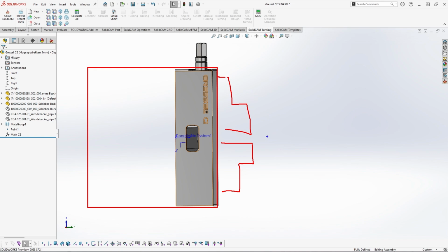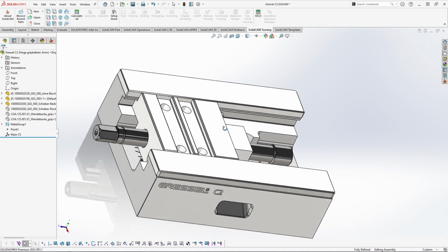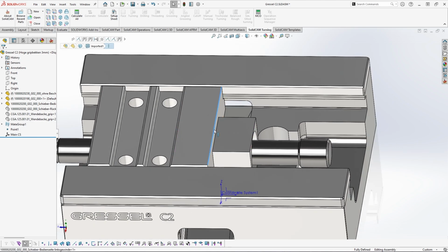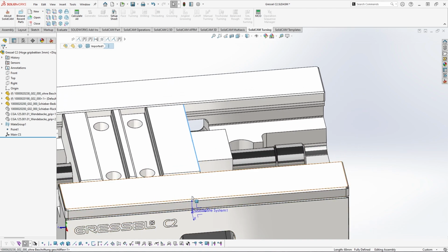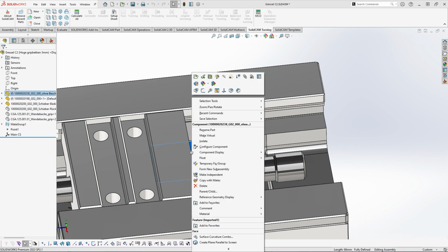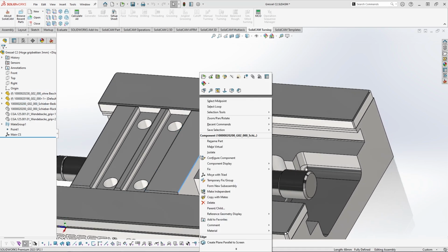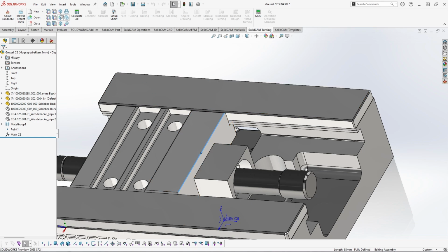What we have here is the z-axis and also the x-axis. These jaws are moving in this direction, so this is the coordinate system that we are looking for. Because of that, and the rule that everything for the jaw system must be in the x-plane, I'm going to create an additional coordinate system that will be rotated according to this one. Let me just refresh this so we can see the main coordinate system. Okay, it will be placed over here on this edge, in the middle one. So I'm going to pick a middle point.